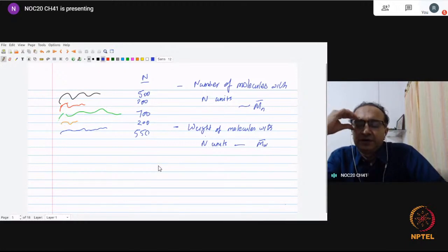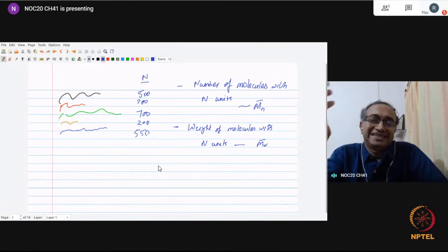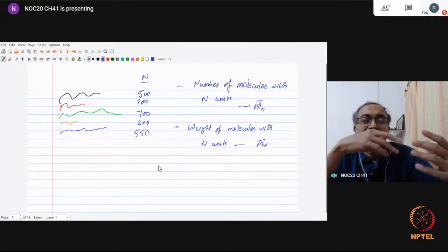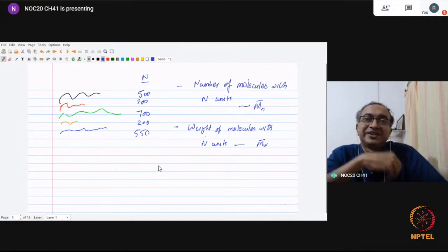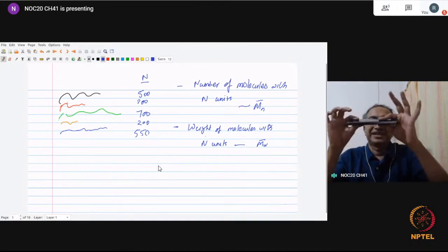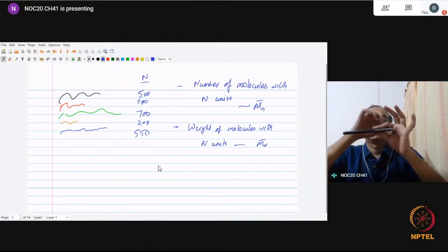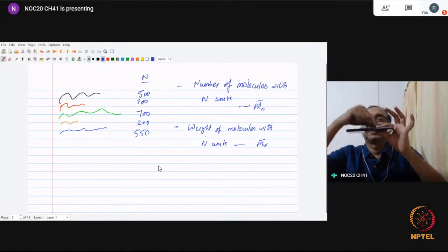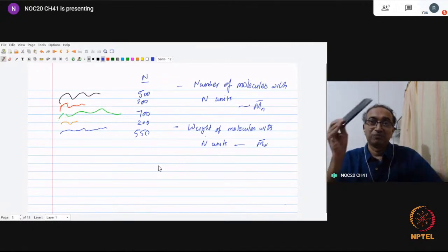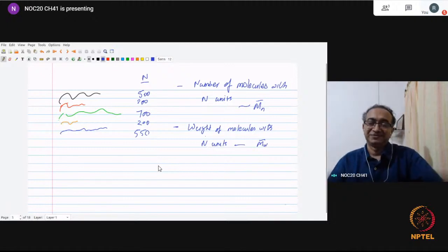Can we find the molecular weight of a thermoset? No, it doesn't make sense, right, Dharmendra? Because in a thermoset, the molecule is just one infinite molecule, because it's joined with crosslinks from one end to the other end. So if I make this whole big object with thermoset, this part of the molecule is connected to this other part. So it's infinite molar mass. This whole block will be one molecule only.